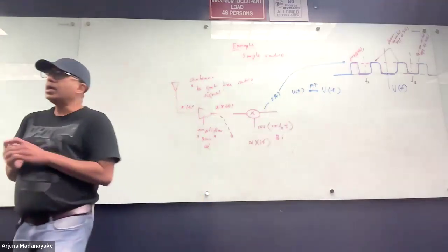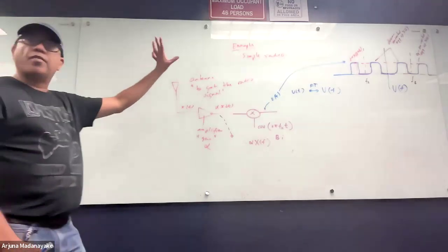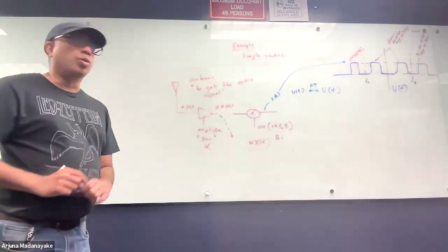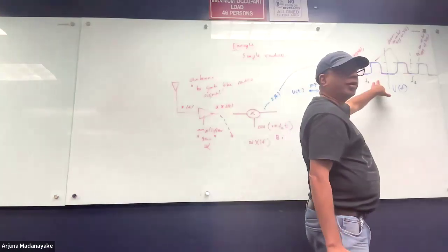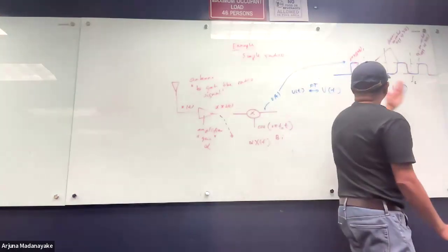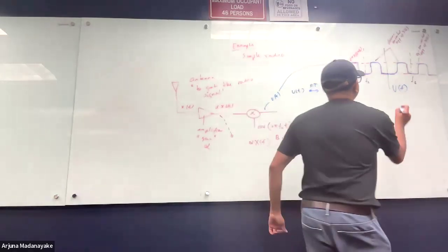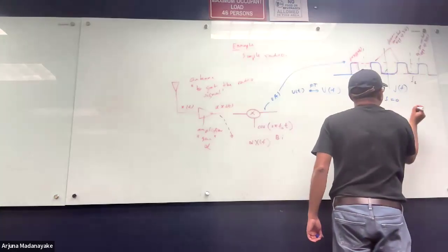Fourier transform, right? So we are visualizing what's happening to the spectrum in the frequency domain by applying the theorems. Now we have two copies, one at a higher frequency, one at a lower frequency, and these are the two images in positive and negative frequency components. This central point here is my f equals 0 axis.